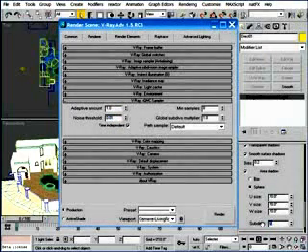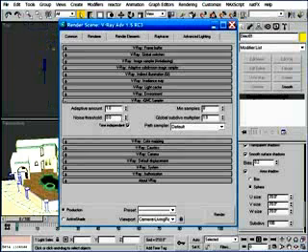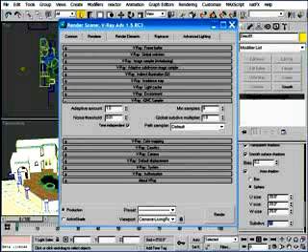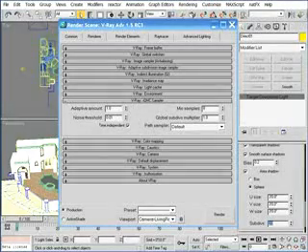So I could set the shadow subdivision to 100 if I did have noise, and if that QMC sampler noise threshold value wasn't low enough, wasn't as accurate as it needs to be, that shadow subdivision or material subdivision setting won't mean anything. So with these last two changes that I made, it didn't seem to have any impact on the shadows from the sun hitting the floor here, but notice a few things.